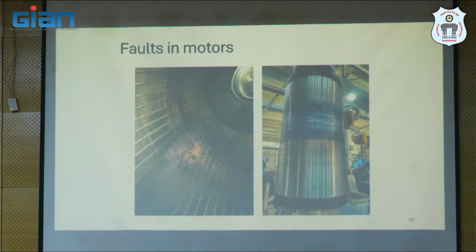So the problem with eccentricity fault is, even though it's gradually deteriorating, it gives us the cushion of time. It's not going to start today and result in a rub immediately. But if we don't monitor it frequently enough, if we don't assess the situation, over time there is a high chance that it may result in rub.